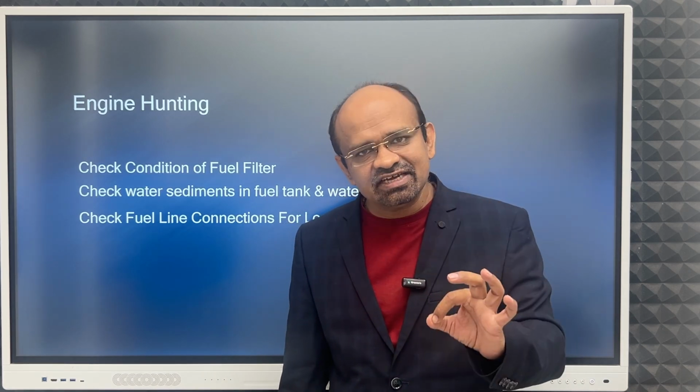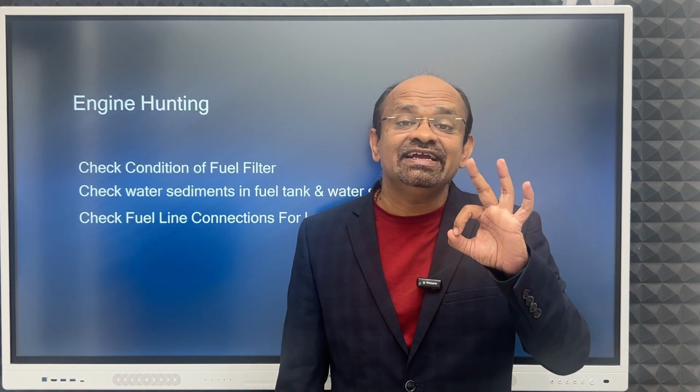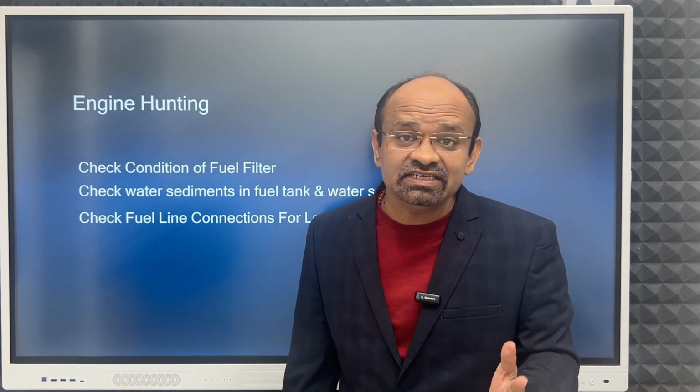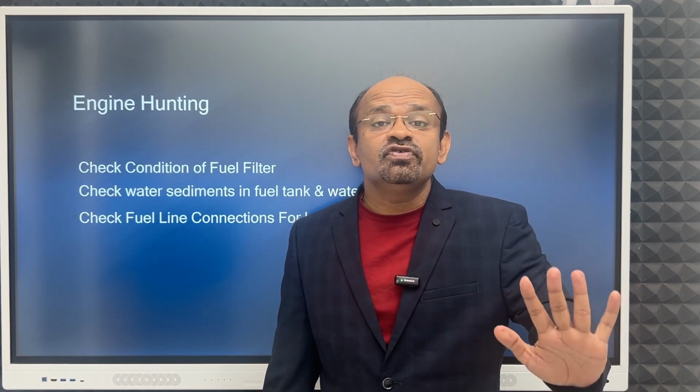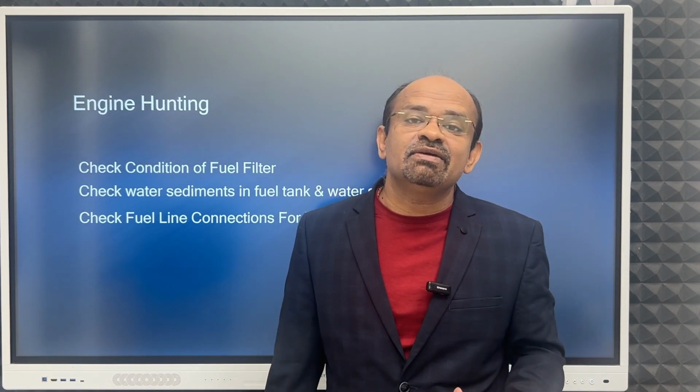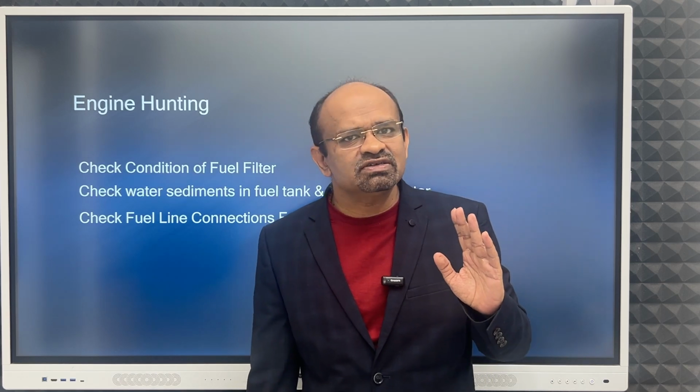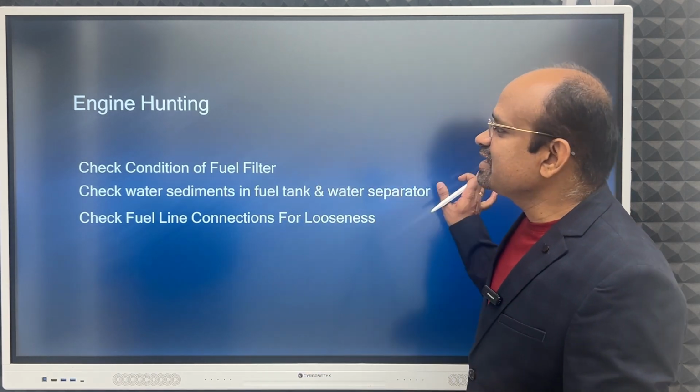That is why you need to check if the fuel line is in the right condition, or if there are any leakages. If leakages are there, the fuel line pressure will drastically come down. Sometimes it will get fuel, sometimes it will not. So that is the reason.